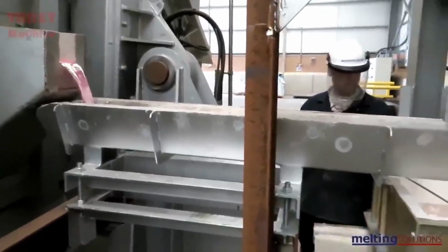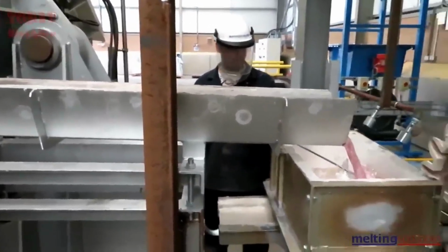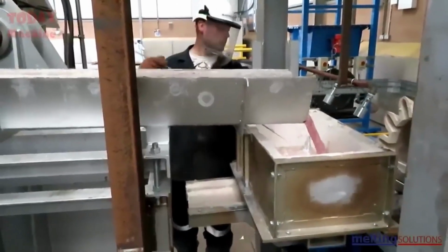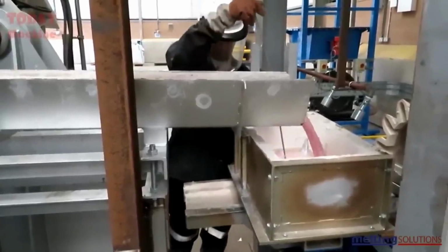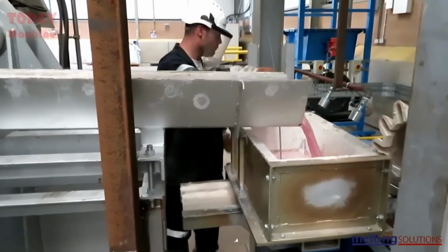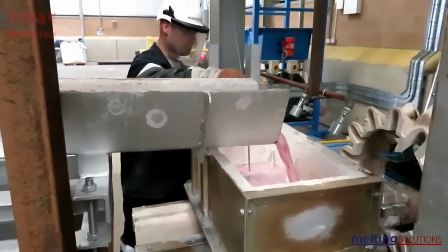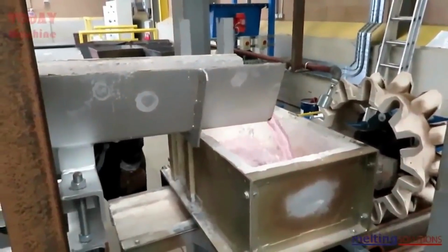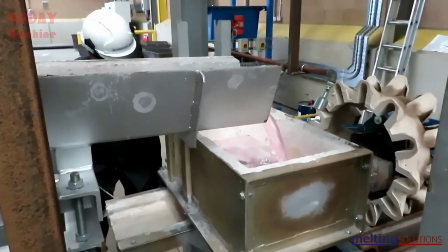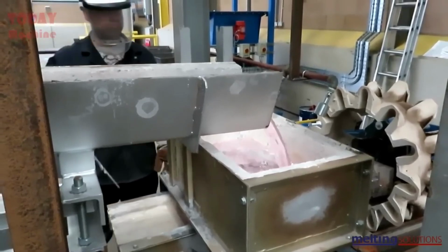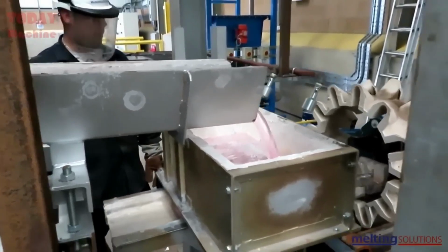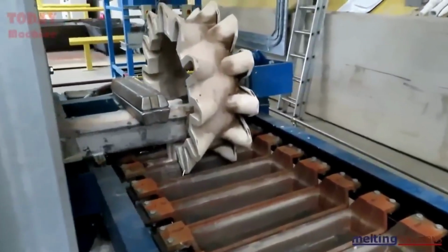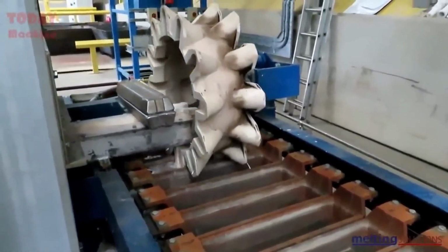The larger pieces of scrap metal are shredded or crushed into smaller fragments to increase their surface area. This process improves the efficiency of subsequent separation and sorting steps. The shredding and crushing step is typically done using specialized equipment such as shredders, crushers, or granulators.